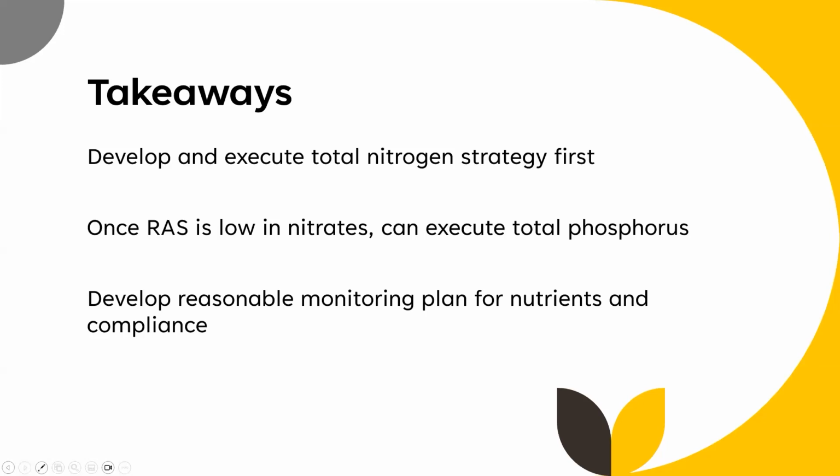If you try going with total phosphorus and you have high nitrates flowing around in your plant, you're unlikely to be successful with that strategy.